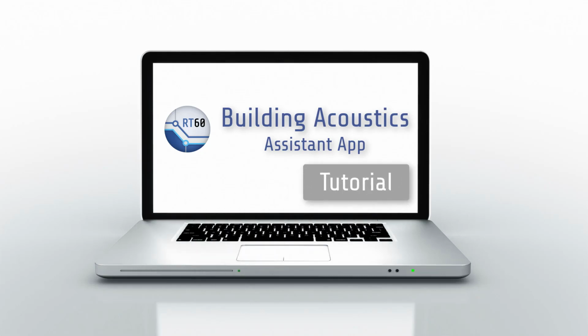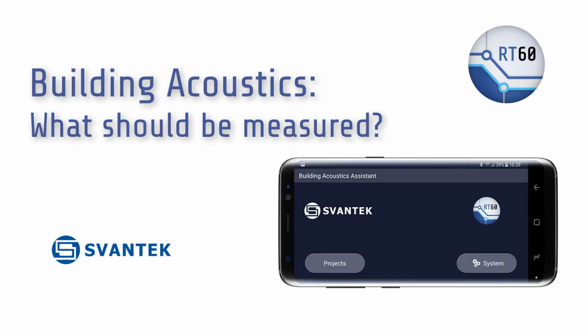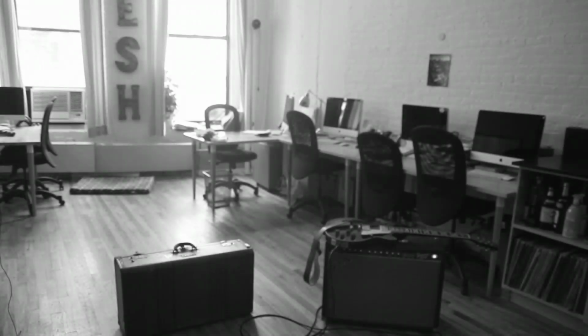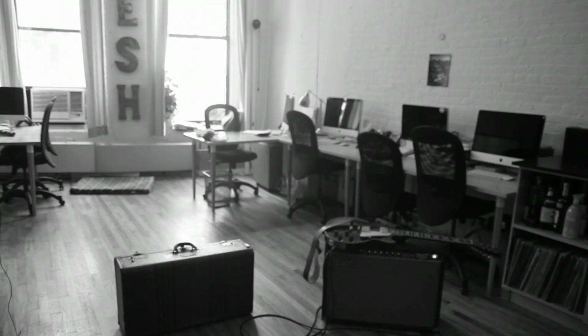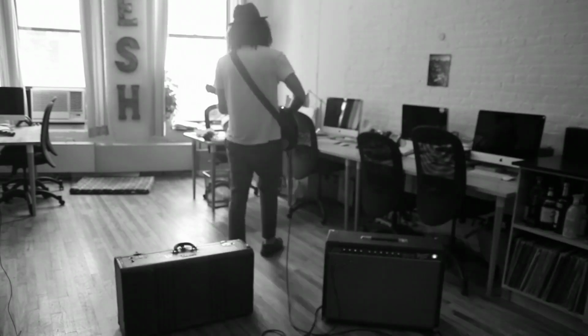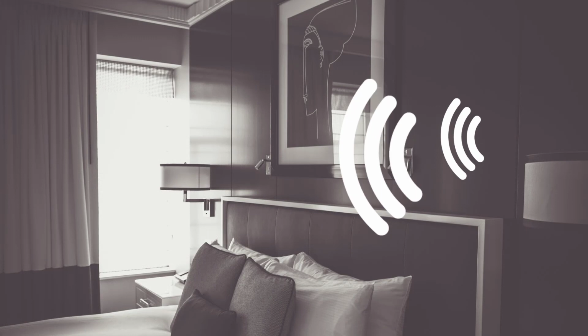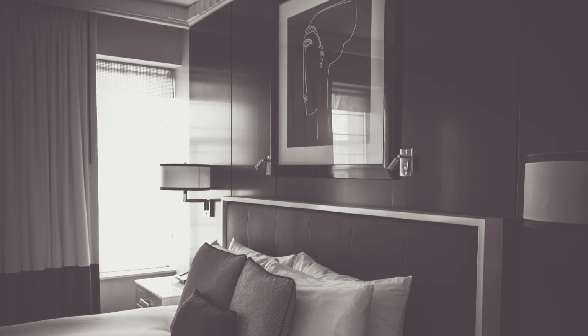This tutorial may answer some of the basic questions asked by the newcomer to building acoustics measurements using Svantek sound level meters with the BA Assistant app. Sound energy does not remain in the room where it is produced, but propagates throughout the building by any available transmission path and intrudes into other rooms as noise. Sound energy is transmitted via the air and structure of the buildings.